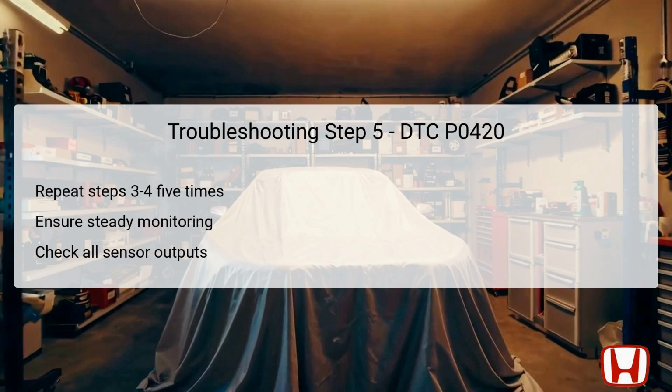You should meticulously monitor the vehicle's speed and throttle position while ensuring that both the secondary HO2S and the PCM readings remain consistent across all test runs. It's this consistency that helps confirm whether the catalyst is truly underperforming or if other extraneous factors contributed to triggering the DTC. Using this repeat testing strategy can reveal intermittent issues that may not be apparent in a single cycle.